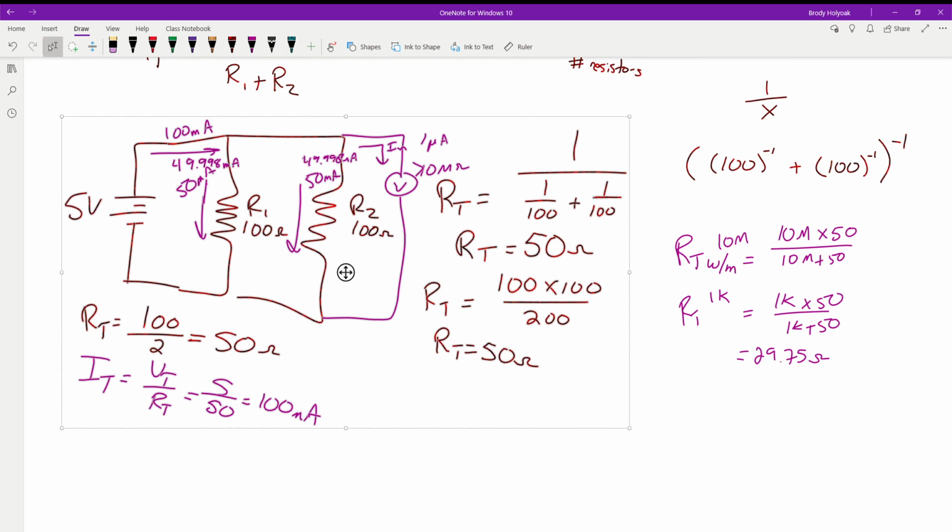Like I said, it's going to be kind of a hard thing to wrap your mind around. But when we deal with resistors in parallel, we have to treat them differently because they act differently. And when you're solving for things, make sure you keep that rule of thumb in mind, that you can't have a resistance larger than your smallest resistor in parallel. Does that make sense? Okay.